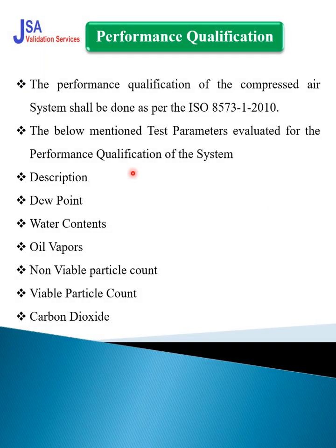Okay, so for performance qualification of the compressed air system, we have to mention the minimum test requirements as per ISO 8573, part 1 to part 10. As per this guideline, there are 10 parts, published in 2010, or we can go for the ISPE guideline for process gases published in 2011.